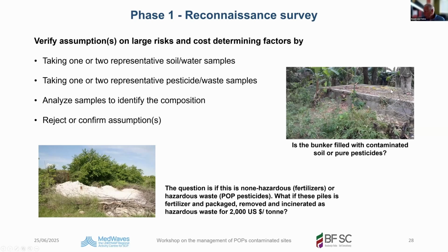Another question: what is in this bunker? Is this bunker completely filled with pure pesticides, or is it filled with contaminated soil? It makes a huge difference in cost. So what we did, we just drilled through this concrete, we took a sample, and we found out that it was filled with contaminated soil, so less costly than if it was filled with pure pesticide.